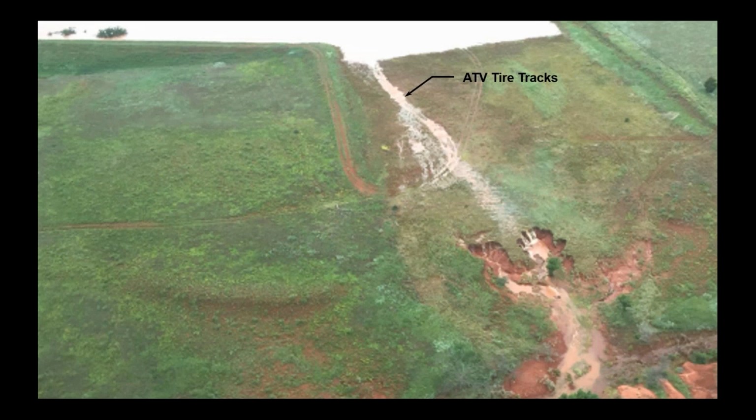What are some reasons why this might happen? Well, don't underestimate the importance and the value of the grass lining. That grass lining really is the first line of defense and provides the erosion resistance or an armored layer over the spillway. And I really like this picture because it shows how something as simple as ATV, all-terrain vehicle activity, how that can impact the performance of the spillway. So here you can see the tracks coming around, going over the crest and also down.